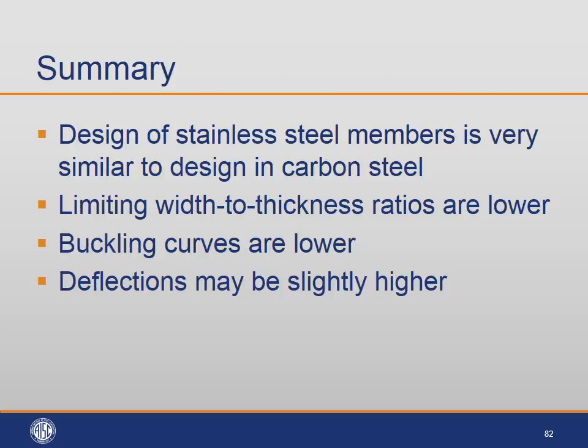Just before we move on to connections, I'd like to summarise the design of stainless steel members. As you've seen, very similar to carbon steel members. Limiting width to thickness ratios are lower, the buckling curves are also lower, and deflections may be slightly higher.